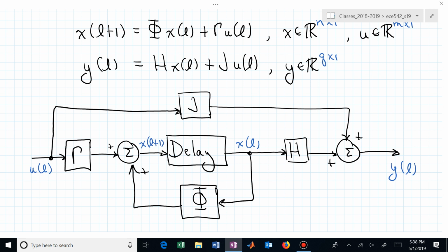And here is how you could now describe those equations, the dynamic equation, which is the first equation, and the algebraic equation, which is the output equation, in a block diagram description. And obviously that delay is a block of delays, because your state vector X is N tall, or N state variable components in your X vector. U and Y could also be vectors. They don't have to be single input, single output, and that's the power behind a state space representation.